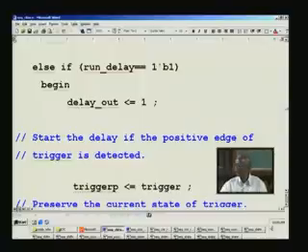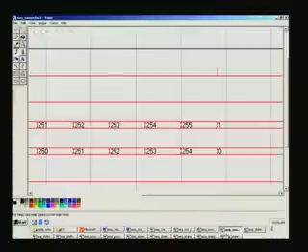In this what we had seen here is 254. In the previous case, had you implemented that one, after 254 it won't become 0, it would go to 255 and next only it will go to 0, because counter reg is activated in the present clock cycle, which will be taken into consideration only on the arrival of the next clock. So in other words, in the previous design it has to wait for the next here.